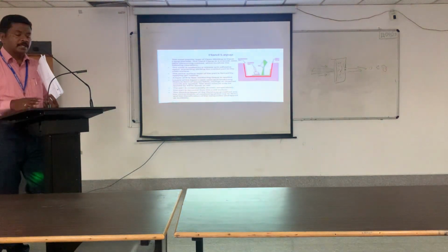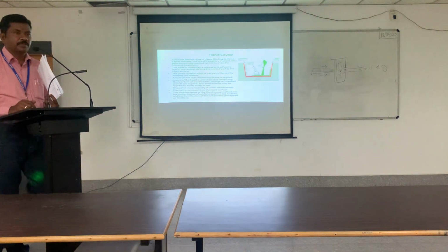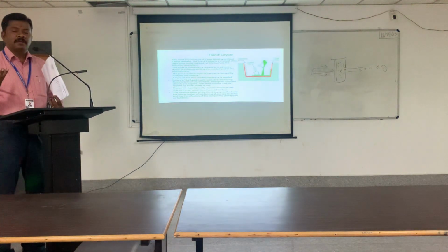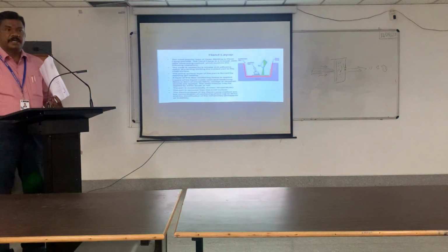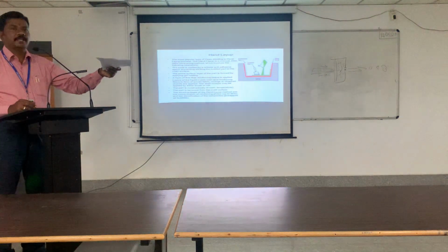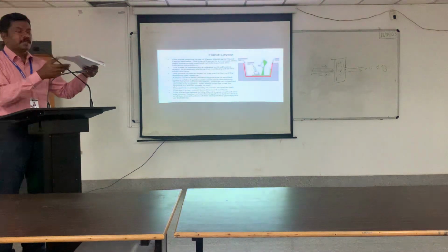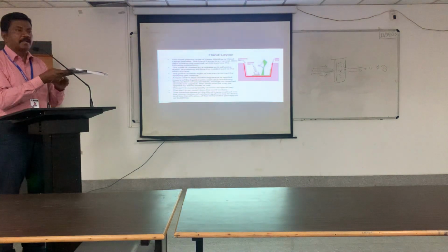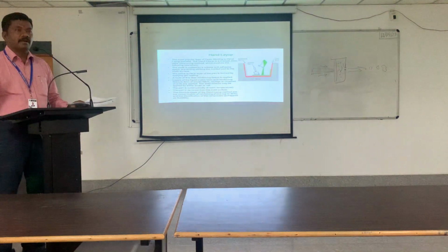Either it may be wax or simply an OHP sheet. Then on top of it, you should take both the reinforcement and the matrix material in the required quantity. If you are going to make a plate of this size with a thickness of 10 mm, say for example, the reinforcement is 10 layers, and the matrix material is 500 ml of liquid epoxy resin.